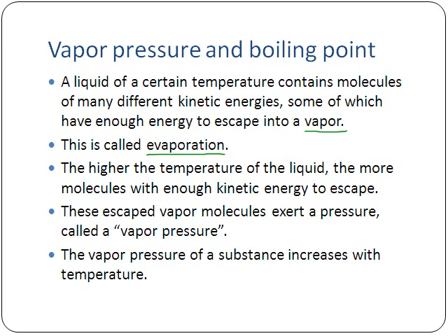Now, if your water was in a closed container, those vapor molecules escape into the gas region above your water in your water bottle. They're up in the gas region at the top, floating around up there. But since they're moving quickly, they're going to run to the walls. When they run to the walls, they're going to impact the walls and create a force. That's going to put a pressure on the walls. And so the escaped water vapor molecules are going to exert a pressure on the walls, and this is called the vapor pressure. So this is our vapor pressure right here.